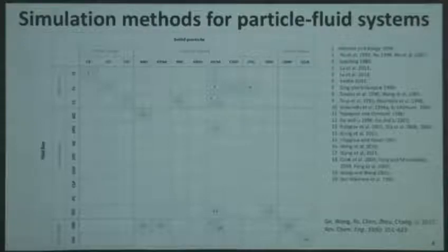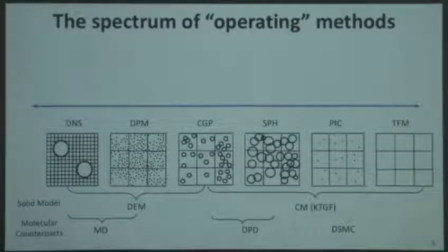But in terms of the operating methods in particle fluid flow, I think in the stream we have the most detailed direct numerical simulation method, mainly based on the particle DEM method and the fluid flow solved by the Navier-Stokes equation at the particle resolved level. And on the other hand, the two fluid model, both solid and fluid, are treated as continuum.